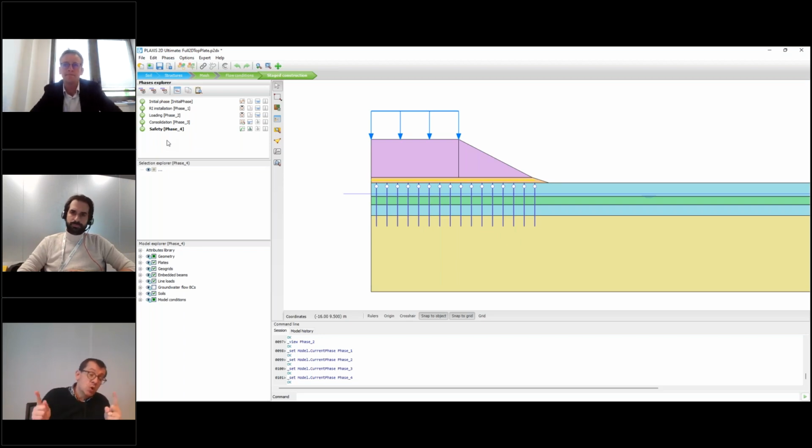And again, usually those dummy plates are relatively short, and they are initially computed by playing with some simple equivalence law on area: compute the area in contact in the plane strain situation, compare it with the area in contact in the real situation, and then fine tune a little bit until you get the perfect match in terms of normal forces at the head of the rigid inclusion. But that will only give you the head of the inclusion. Then you need to continue the calibration such that the development of the normal force is accurate over the entire element length.